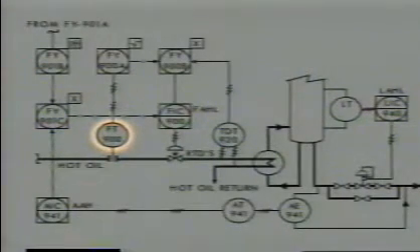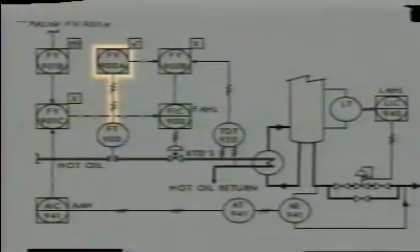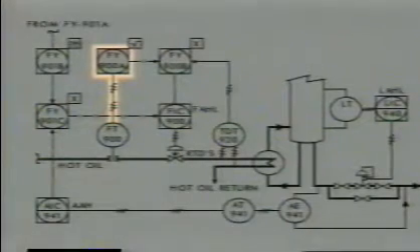This is a discrete field-mounted instrument located in loop 900. The flow transmitter sends an electrical output signal to the square root extractor, also in loop 900. The letter A after the loop number indicates that there is more than one computing function in this loop.